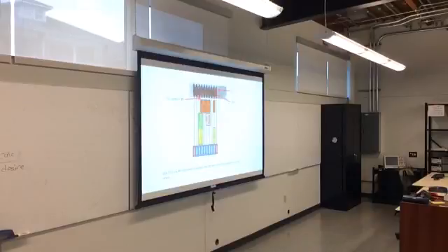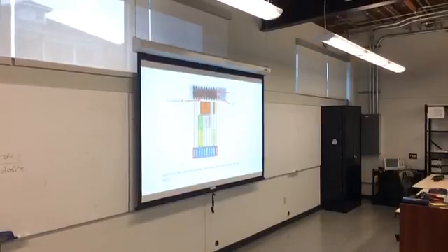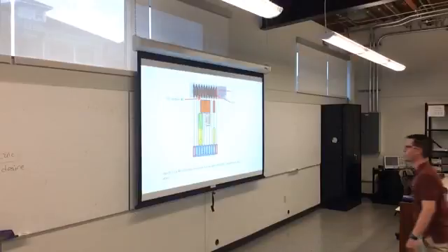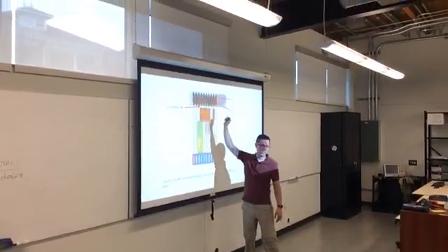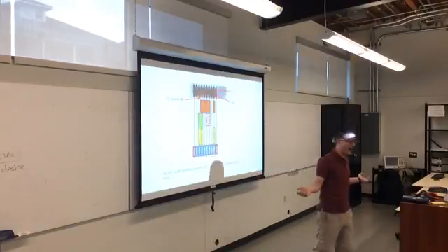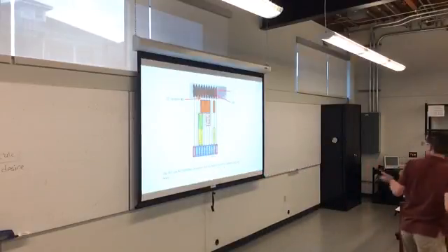I wasted probably like 20 to 30 hours, and over a year ago couldn't do this, because I never said, let me change what pins I'm on. Because like, why should it matter? Why does it matter if you're on location 0 versus location 1? It turns out it does. I have no idea why. I have no explanation for why the exact code works on these pins, not on these pins. Maybe it's the way the board's made. No clue. You need to use location 0, otherwise if you use location 1, it'll never work.